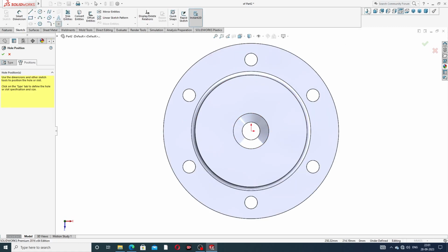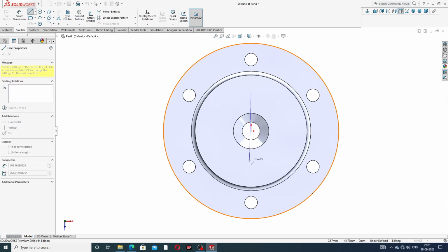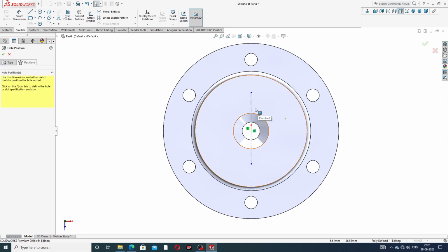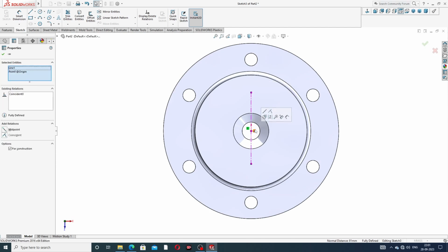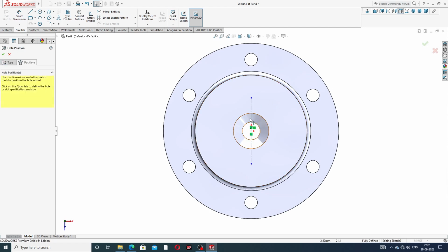And this is sketch normal. Okay, and drawing a reference line. The reference line is perfectly drawn here, because this uses a mid plane. Okay, select this line and press the control button and select this point and use a mid plane. Okay, and all is perfect, and the dimension is mentioned here.